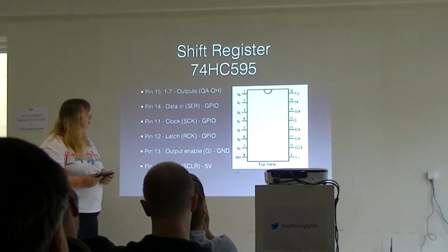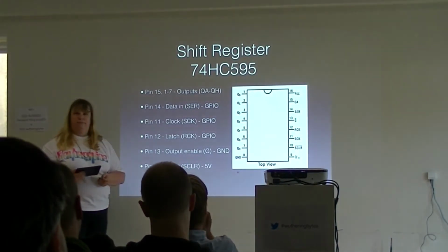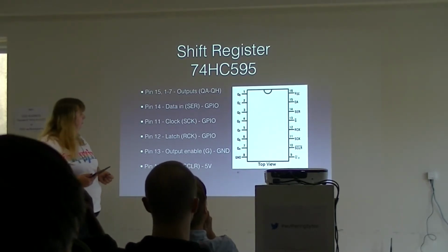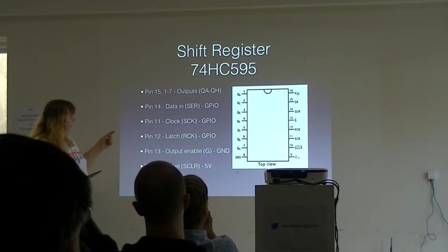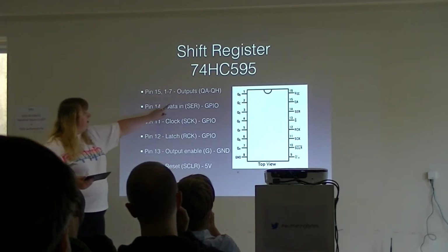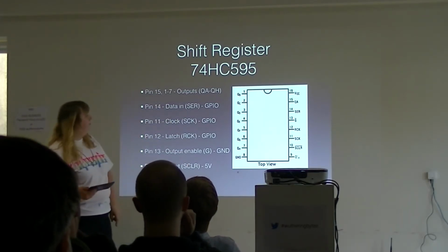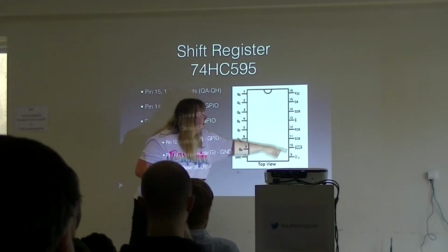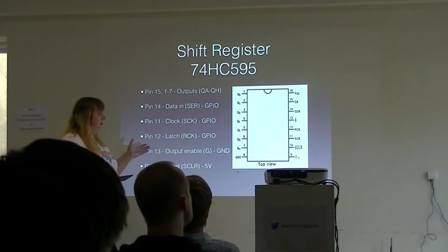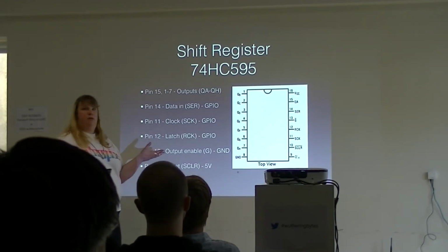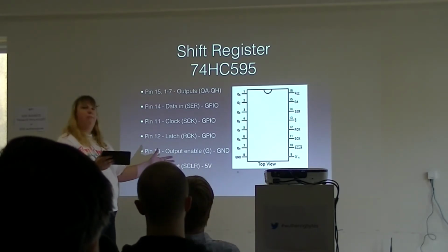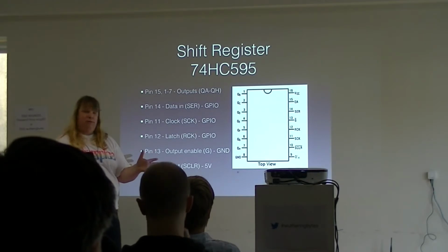And this is an off-the-shelf shift register chip. So going back to our previous diagram, we have a couple of extra pins here which we won't get worried about for a moment. So we've got our data, pin 14, data and clock from that diagram. Now, this has also got a thing called a latch in it, which basically says, remember what state I've set you to.